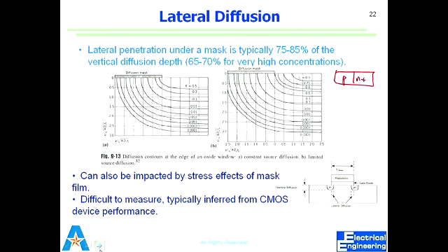What we do is we make them, so I'm keeping the gate. This is where I will come back again. But what we do is we make them probably deeper, a little away. Then what we have is what we call protrusions. There's a specific word for them. So we have this even shallow doping areas for source and drain. So this is what causes this region to be very small.